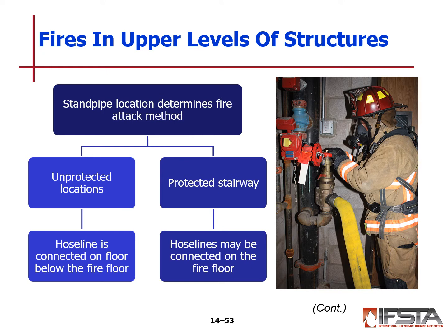Your standpipe location will determine your fire attack method. In unprotected locations, your hose line is connected on the floor below the fire floor. In a protected stairway, hose lines may be connected on the fire floor. And in our protected stairways, this gives you the option of flaking out less hose. You're going to use less hose and make things a lot faster.